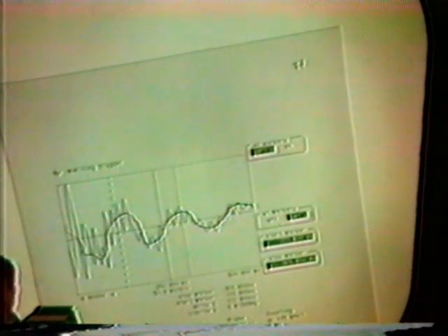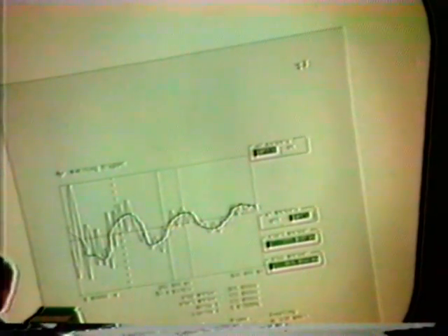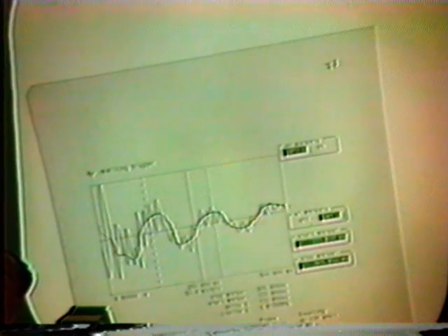So it is not surprising that if the spark is modulating the ringing frequency, the spark is adding energy there very clearly. This I know since I was a radio amateur. When I wanted to modulate my carrier, I had to add some extra energy there. So this is not surprising. It's very clear that the signal is modulated, so somebody somewhere has to add extra energy. The amplitude of this extra energy depends on the amplitude of the modulation versus the amplitude of the ringing frequency. In this case, you can see it is about the same order of magnitude, so the energy of this oscillation is doubled here. It's about 200% in excess.